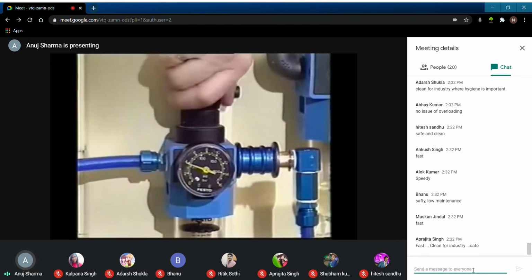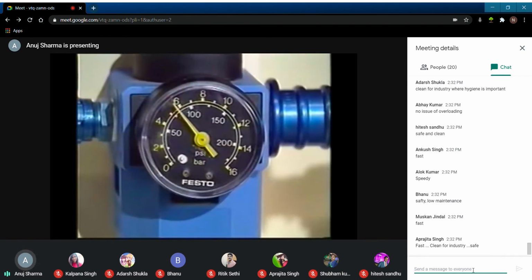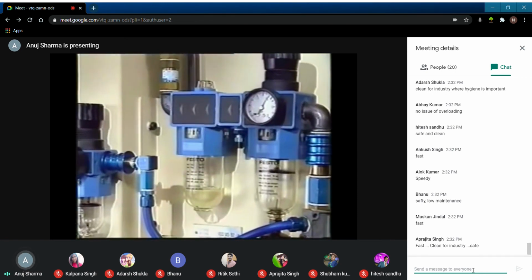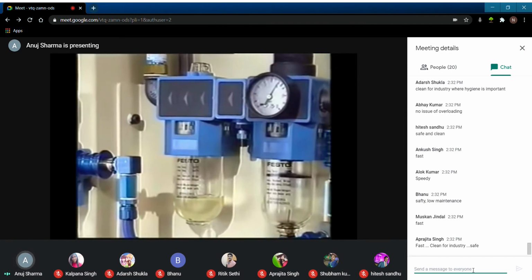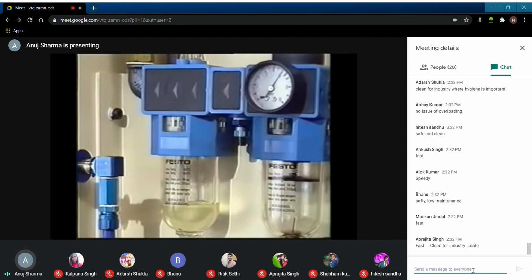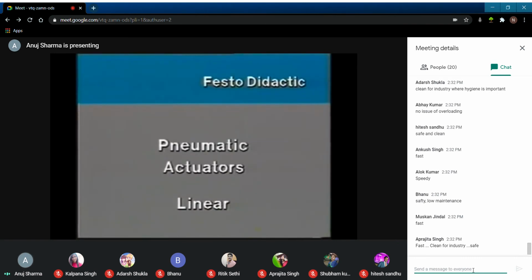Air pressure in the distribution system is normally higher than that in the machine circuits. The pressure regulator on the service unit controls the pressure entering the machine. Some pneumatic systems use components that require lubrication. The lubricator in the service unit, when filled with oil, adds an oil mist to the compressed air, but oil should not be used in applications requiring sanitary conditions.